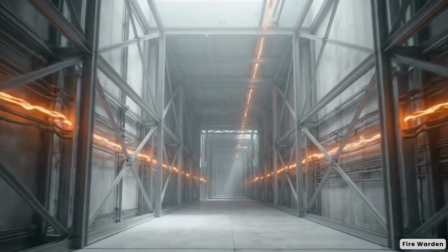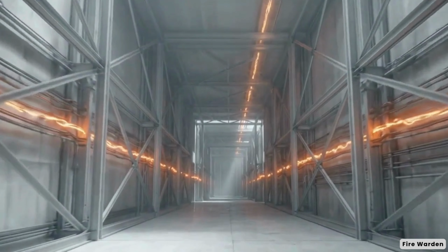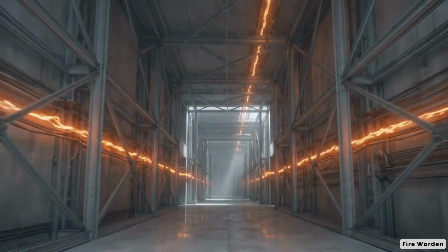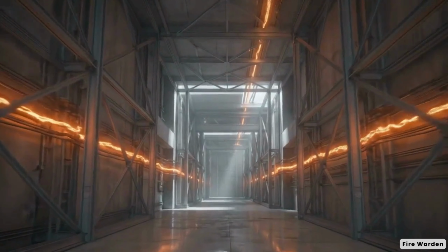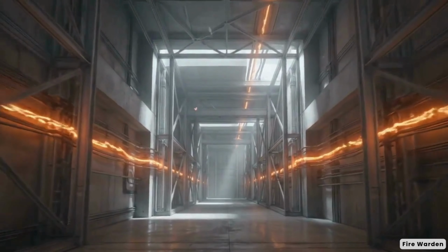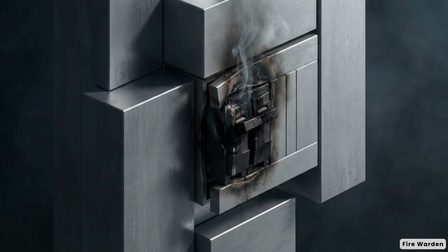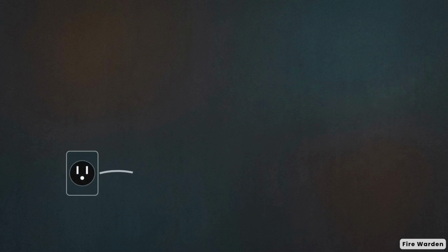In maintenance areas, we encounter hazards that generate high energy. This wireframe reveals electrical conduits pulsing through walls, carrying power across the facility. When these circuits are overloaded, they enter a state of thermal runaway, generating excess heat faster than it can dissipate. Daisy-chained power bars are prime culprits.